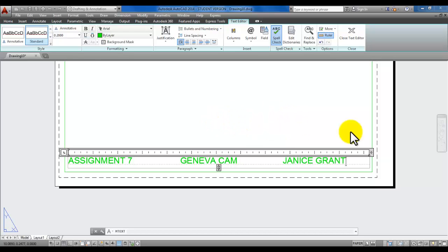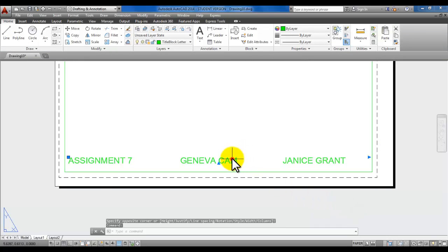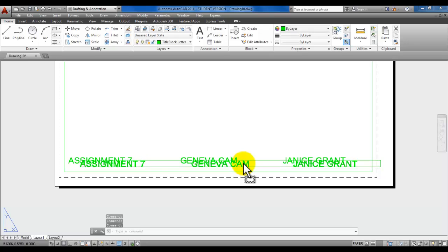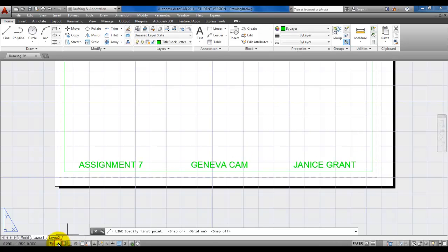Okay, then click outside in the space and maybe select it, move it over so that it's kind of lined up. I'm going to go ahead and turn off the snap. I will turn on here the object snap, which is the 6th icon, and polar tracking, which is what I use for straight lines. Some of you like to use ortho. It's up to you. But what I like to do is track from this corner.